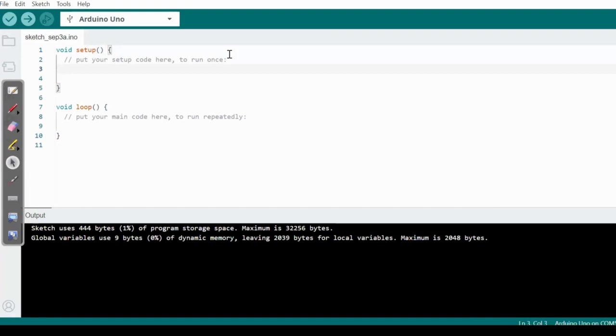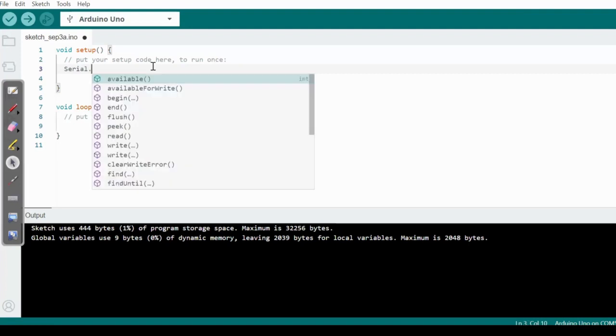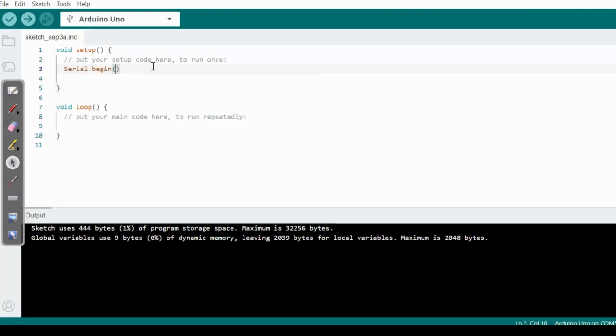So what I will do is I will just say Serial.begin(9600). At this rate, Arduino communicates with our system.